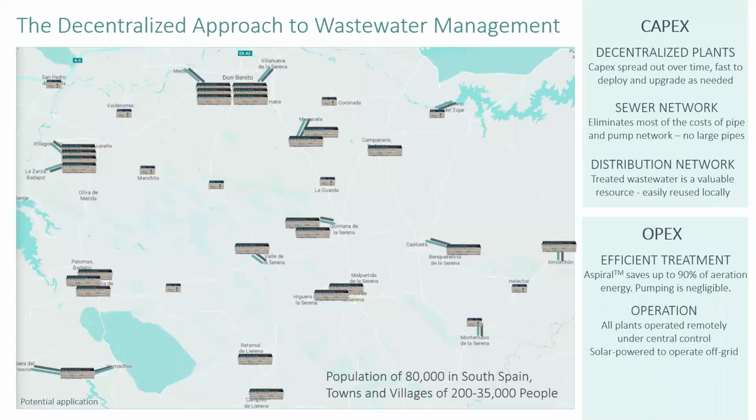And then there's much less pumping of wastewater and water, and the maintenance as well as the routine operation could have a customized structure such as mobile teams running around carrying standardized replacement parts to take care of any failure, which would be easier than looking for the failure along a system of piping.